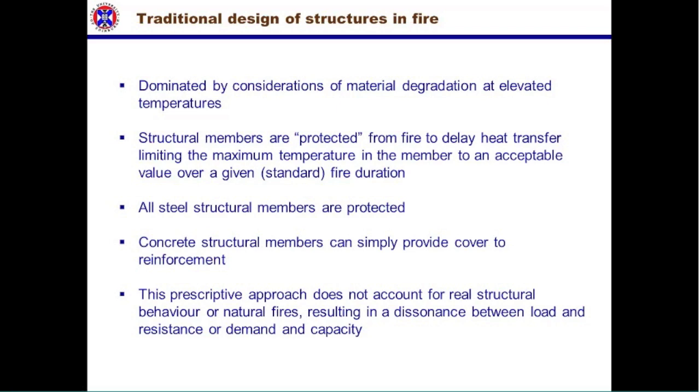Because of that, structural members are protected from fire to delay heat transfer, limiting the maximum temperature in the member to an acceptable value over a given fire duration, which is designed to be a standard, which is not really an actual fire.